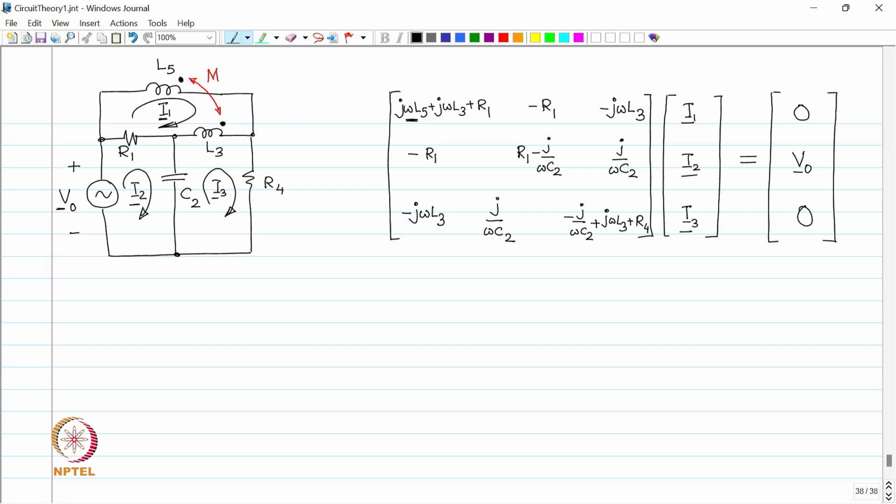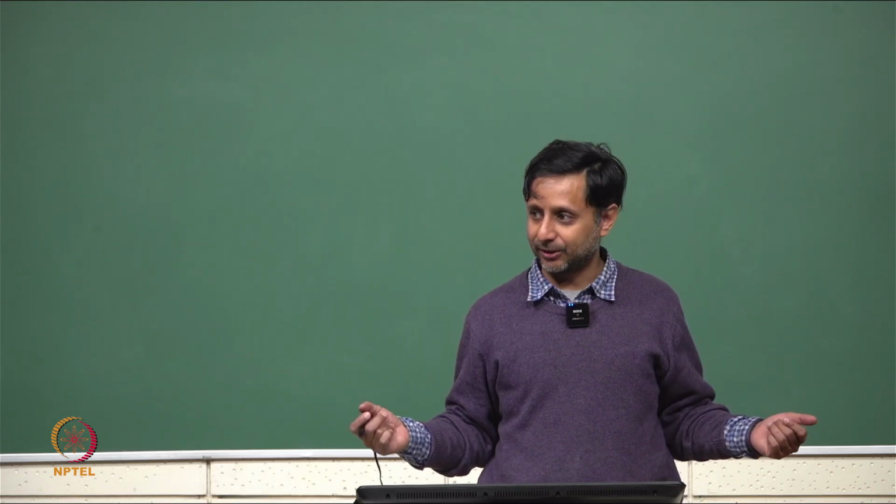So, if you notice, let us put some symbols. I have put dots, let us put these triangles over here. Okay. Just to make things clear, the dots look similar and the triangles also look similar. If the dot terminals are coupled, then the triangle terminals are also coupled.